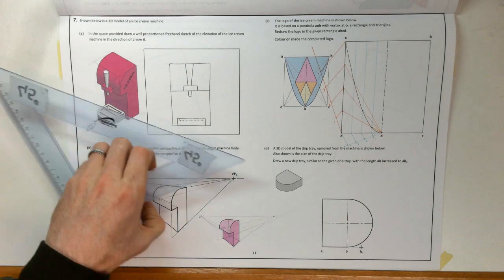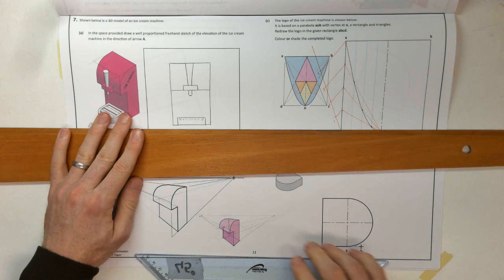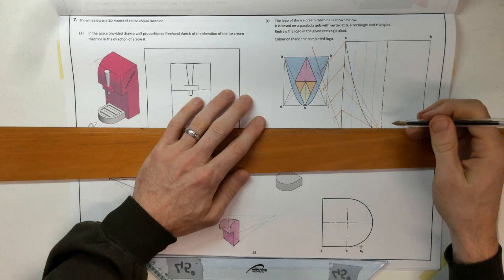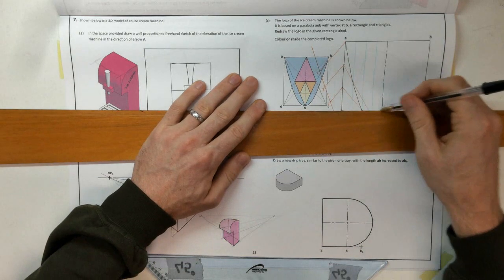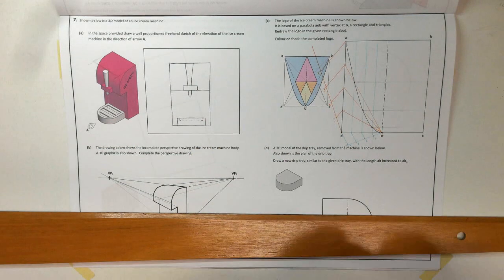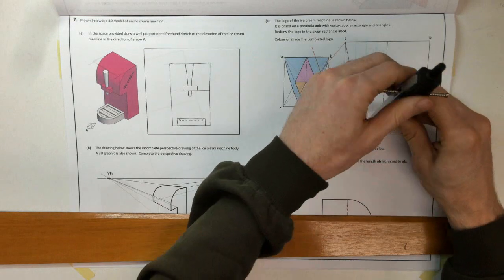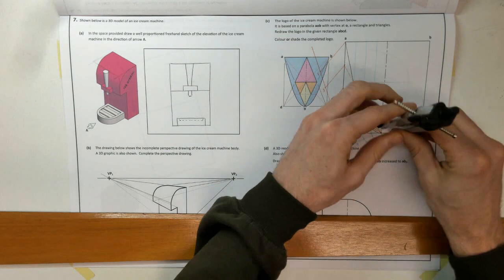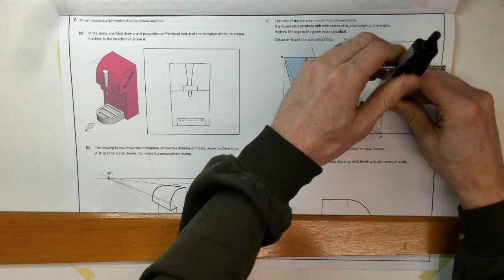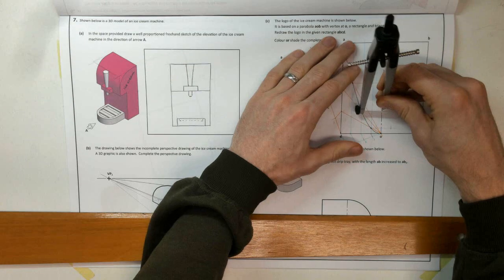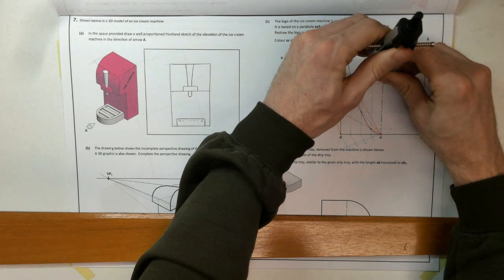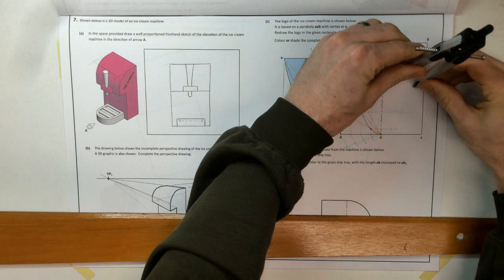Okay, and to find it on the opposite side, I'm going to use axial symmetry. So here's my axis, stand true. All of those at 90 degrees. Compass, set it to that distance, swing through, set it to the same distance here again, and there to there.